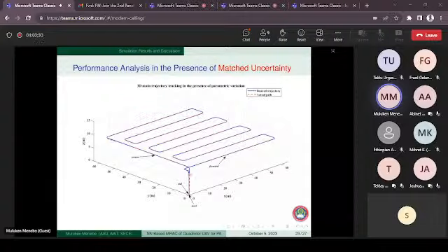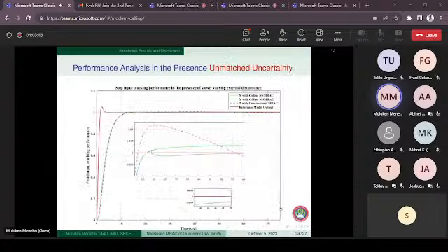As you can see from the figure, when the system is affected by much uncertainty, the controller doesn't lose its performance. The actual trajectory perfectly tracks the desired one, right? The third scenario is injecting gusty wind into the system as an unmatched uncertainty. Some comparison is also made right here. This response is the conventional model reference adaptive control response, right? This is the offline neural network based response. This is the green one.